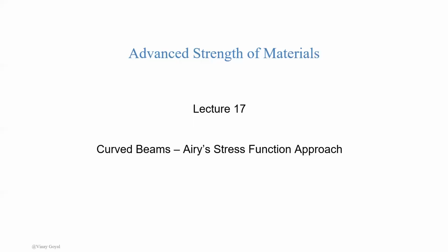Covering curved beams. And the first approach I'll be teaching curved beams is using Airy stress function again. And to back up a little bit, this is yet another application of Airy stress function. The idea here is that with Airy stress function, you satisfy the equilibrium equations exactly, and you satisfy the compatibility equations exactly. And what you're doing here is coming up with a stress function that's able to satisfy the boundary conditions. By imposing those boundary conditions, you're able to solve for the unknown coefficients in the problem. And that way you're able to solve the problem of elasticity in a convenient way.